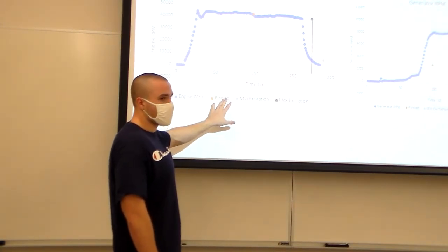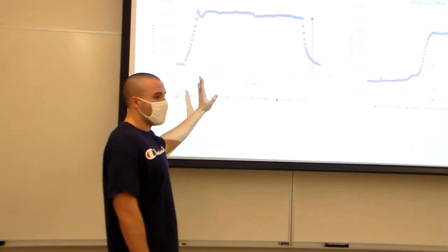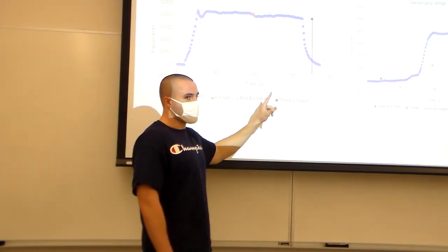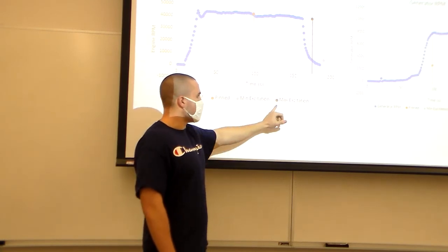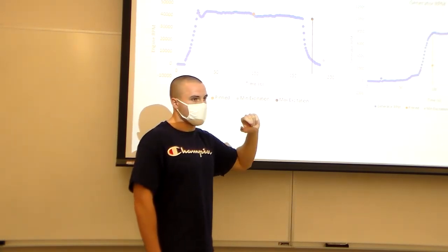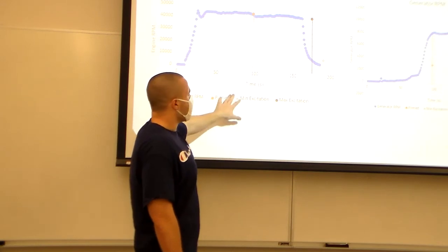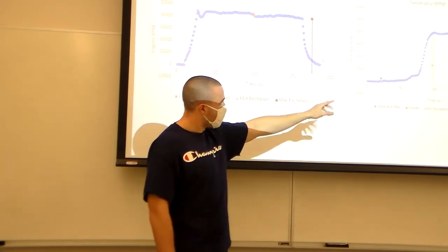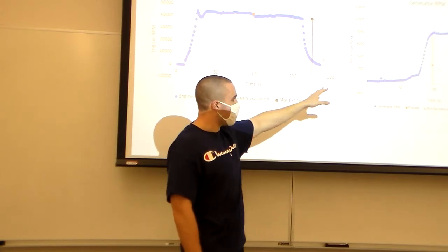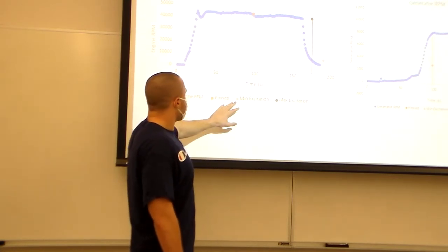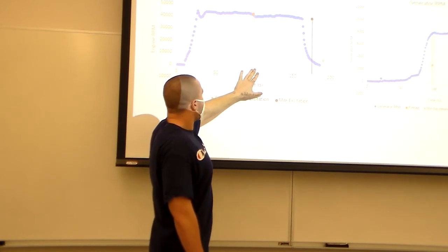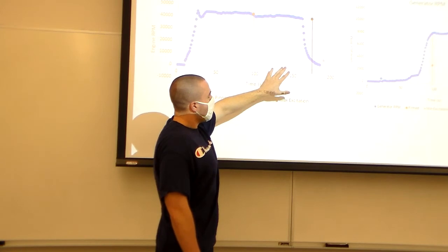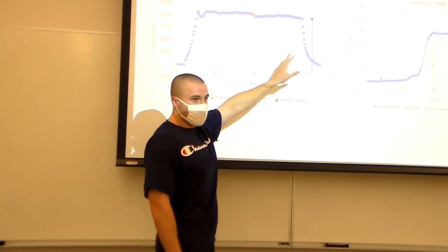And so pinned is the initial point where you're running the engine up the throttle to reach steady state. Minimum excitation is when the least amount of current is produced by the generator, and maximum excitation is where the maximum amount of current is produced by the generator. And so I located those 3 points, and they're the same points in time for all of the plots you're about to see. And what that shows you is where the RPMs of either the turbine or the generator are at this point.